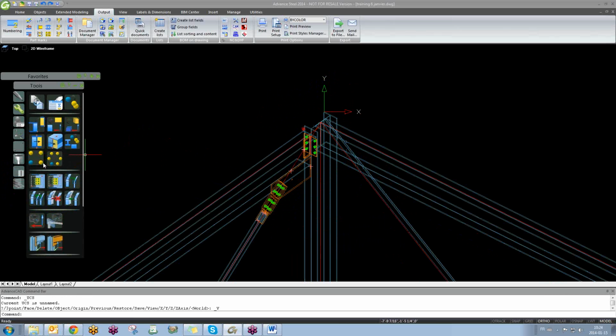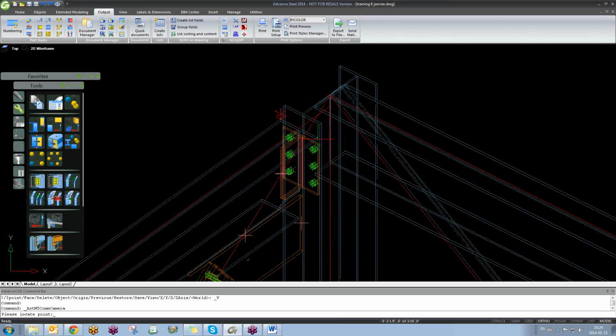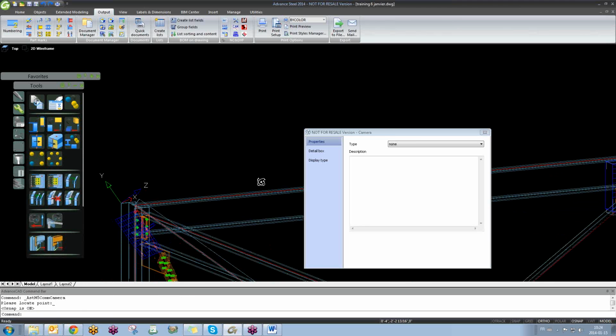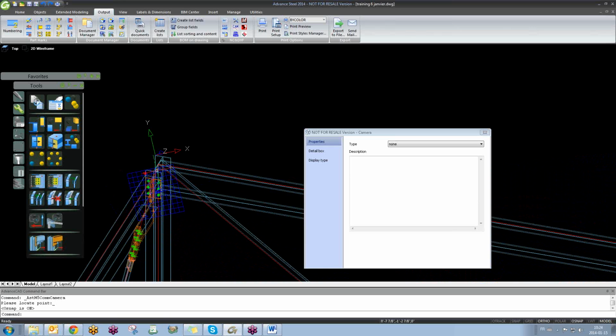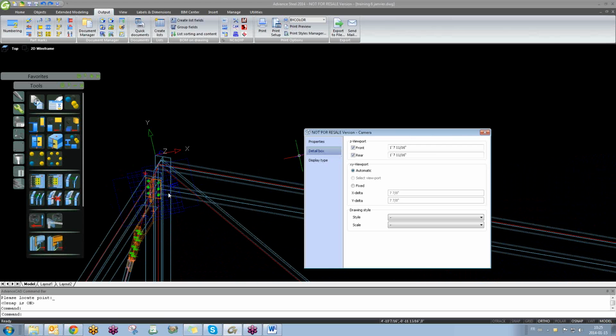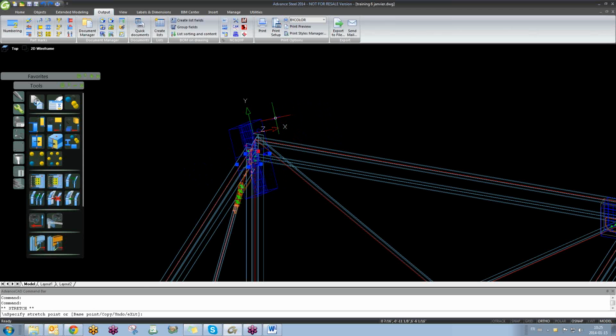So you have to put the camera here and create the camera. So you see the camera, which way it's created. Now you only have to determine your box by clicking here. Set it fixed, don't let it be automatic, because it will give you the wrong results. Now just redimension your camera. That will work.